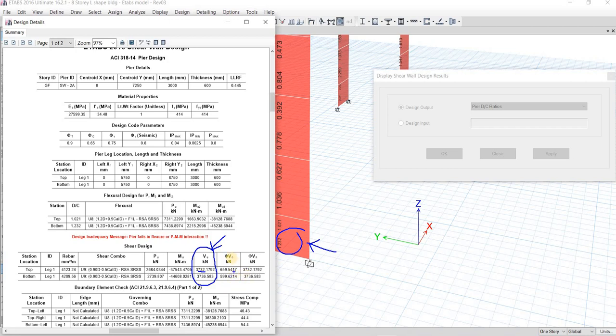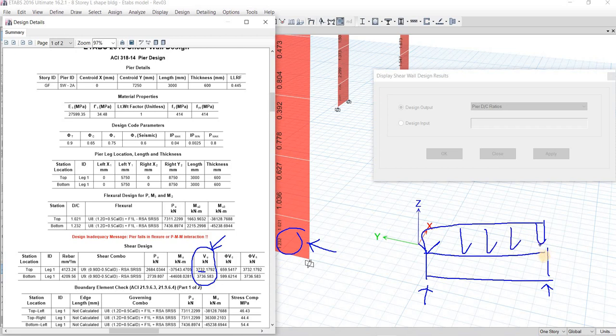Then to determine the thickness, just like for the shear, so this is a shear wall. If you remember how to deal with the shear for the beam, let's say this is the beam, you have a reaction, of course, you have a Vu, you have a load here. Let's say I'm talking about the beam, so it will crack sometimes like this. Yes, this will become the crack failure. So same for the shear wall, it will crack like that.